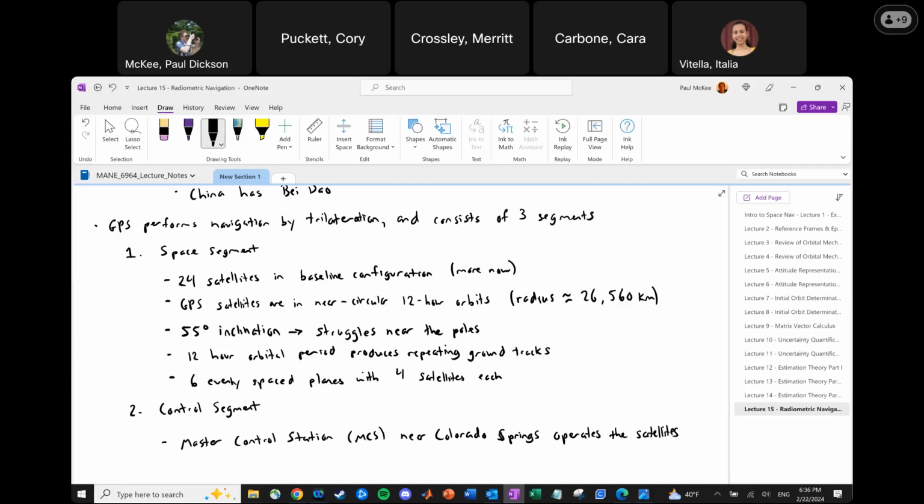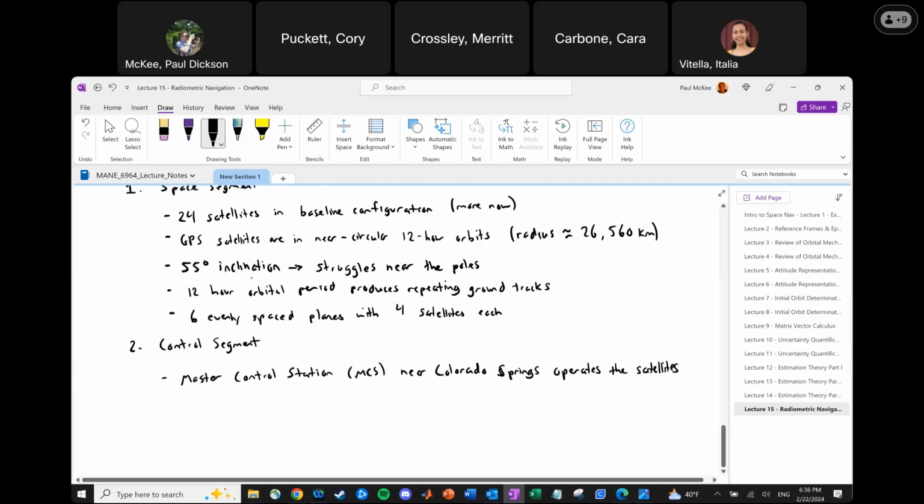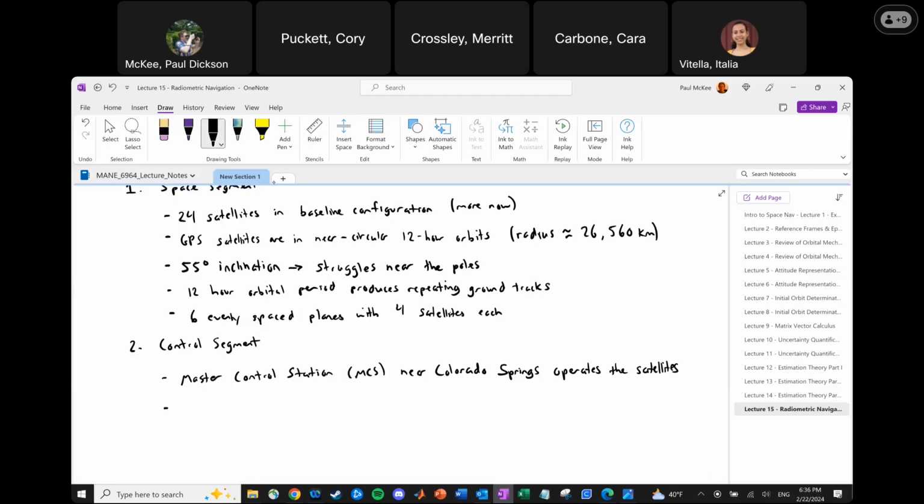There is a constant need, and this is something that I think a lot of people tend not to think about. When you're doing your GPS-based position estimation, your uncertainty in where you are cascades from any uncertainty that there is in where the spacecraft is. So we need to have unbelievably high accuracy knowledge of where every GPS spacecraft is all the time, to within a nanosecond, right?